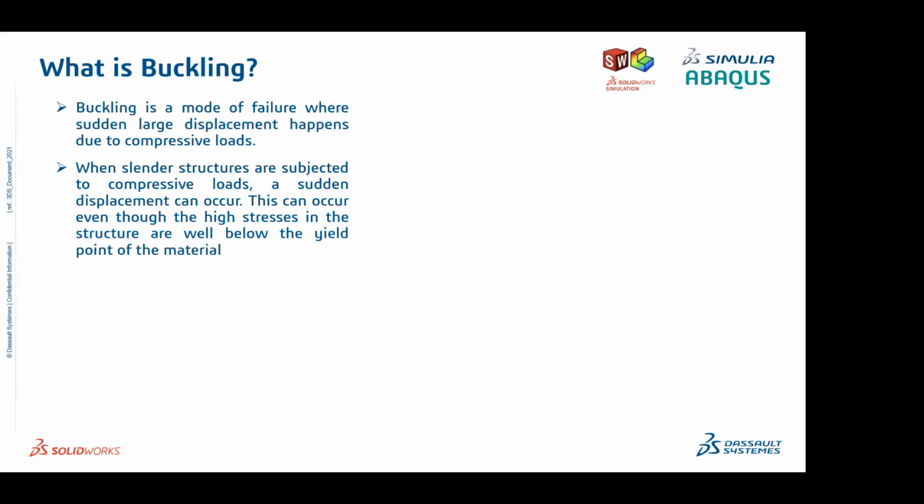and when the ratio is such and a certain compressive load is acting on it, there is a chance of having a buckling failure rather than a yield failure. So based on the loading condition, rather than permanent deformation, there is also a chance of buckling failure.